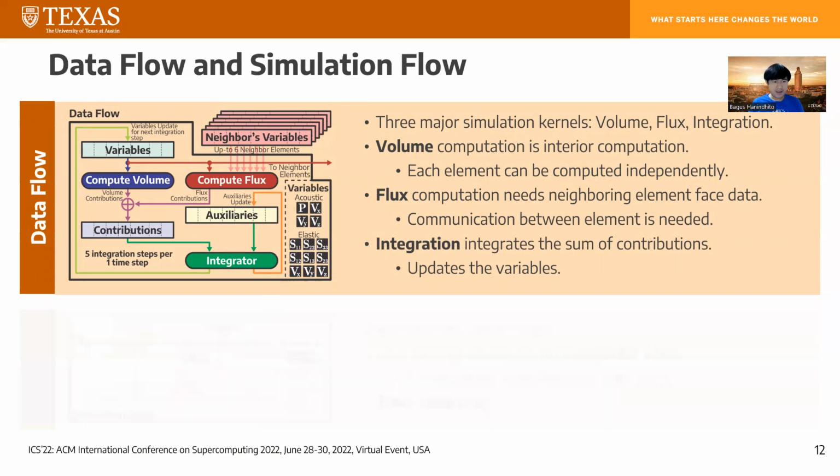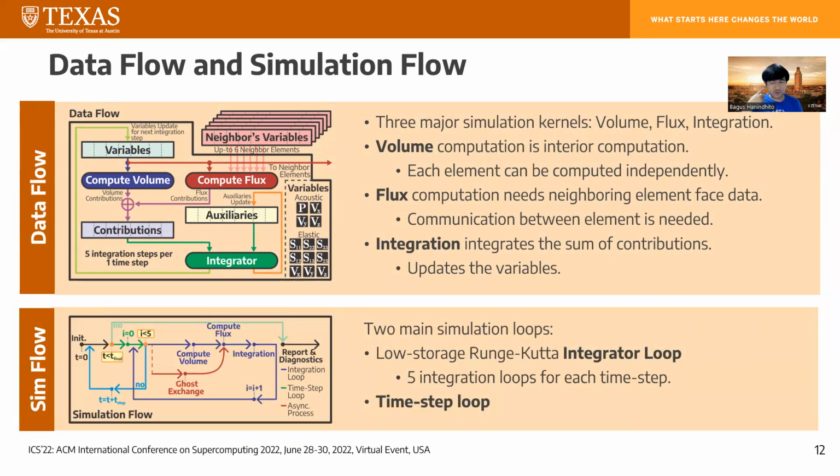The integration will integrate the sum of contributions, that is the volume contribution and flux contributions, to update the variables. Our simulation flow consists of two main loops. The inner loop is the integrator loop using LSRK4. There are 5 integration stages for each time step. And then the outer loop is the time step loop.